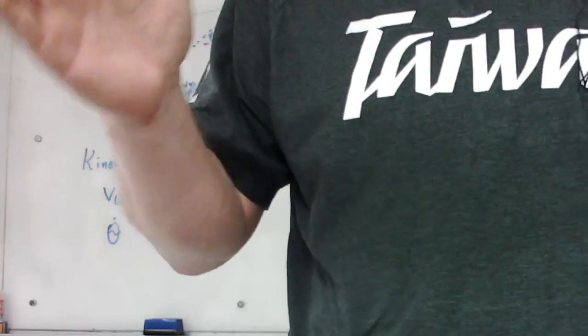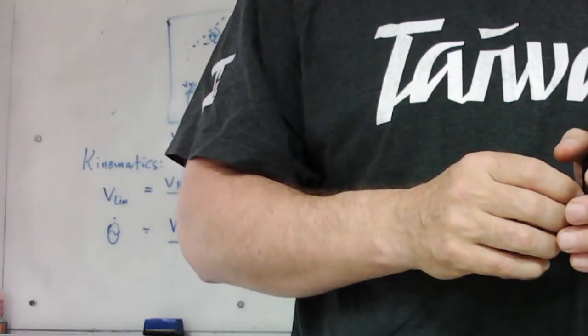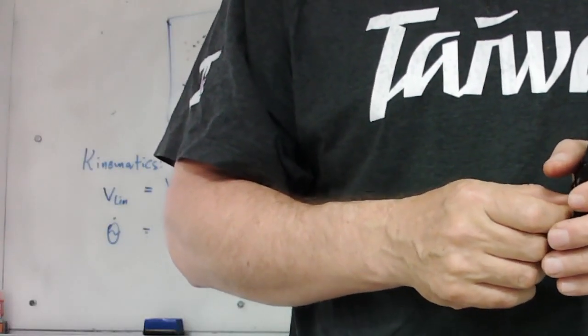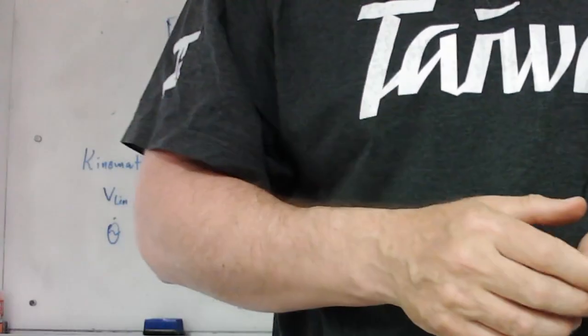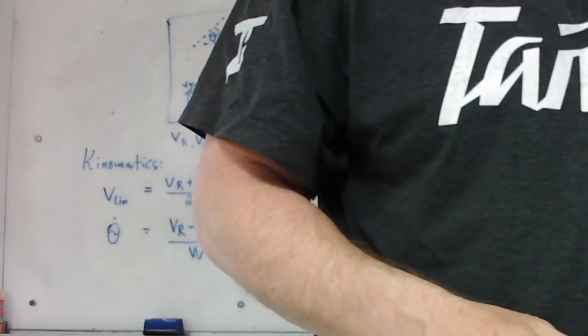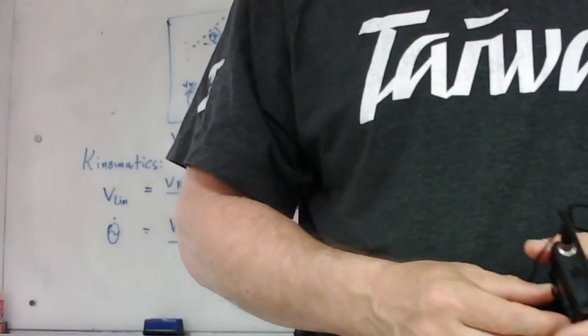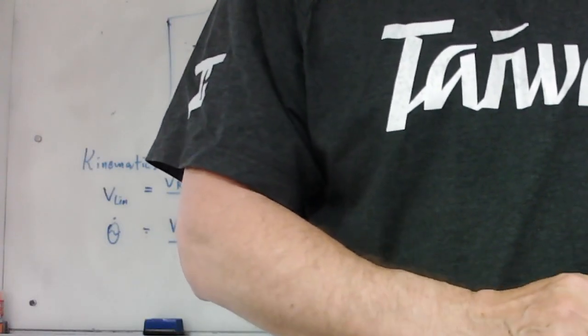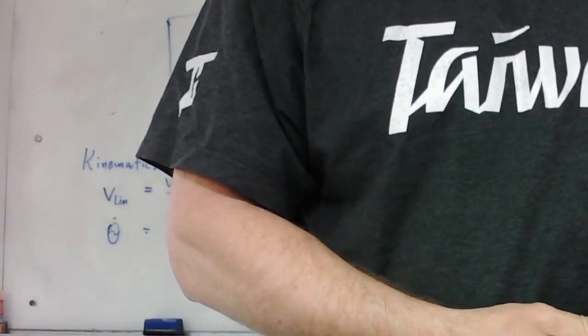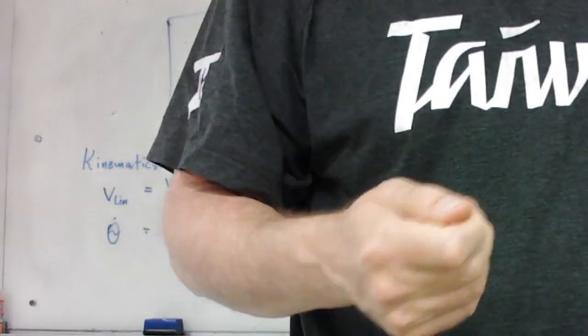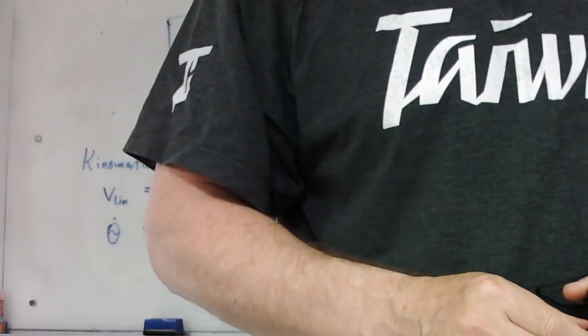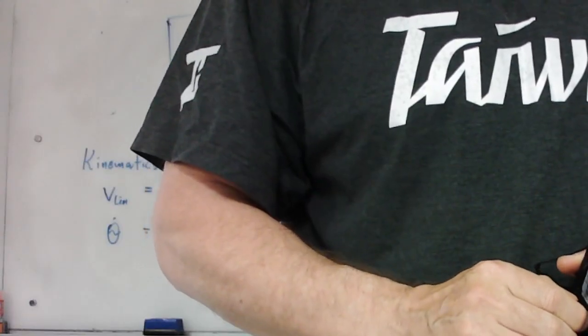You don't say drive forward by 10 centimeters, you say drive forward at 1 meter per second. And then you need to check how long you keep the motors turned on. With the robot, one of the problems is that we cannot just send go forward by 50 centimeters. All we can do is turn the motor on, wait, and turn it off,